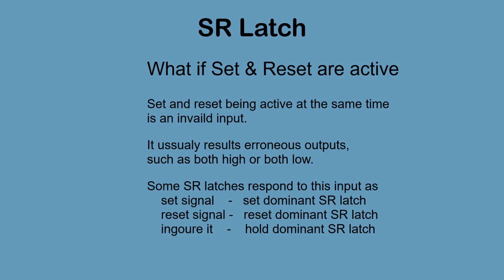You may be wondering, what happens to an SR latch when set and reset are active at the same time? Well, this is generally considered to be an invalid input. It usually results in erroneous outputs, such as both high or both low. Some SR latches respond to this input in one of the following ways.